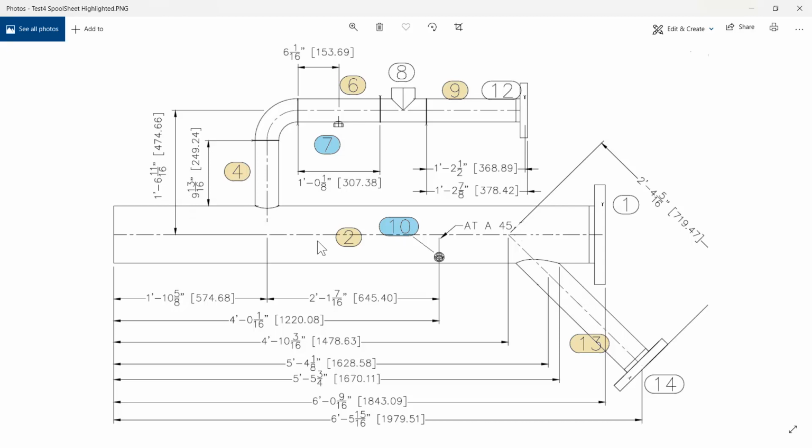We have a run pipe here too. We want to import 4, 6, 9, and 13. By looking at the intersections of these pipes, 4 and 13 onto 2, for example, we want to infer both the set-on type of saddle that we're going to create and the hole that we're going to create on pipe 2. Now in PCF, and most CAD systems, you're typically not actually creating the holes in the CAD system. We're creating the holes when we do the import.